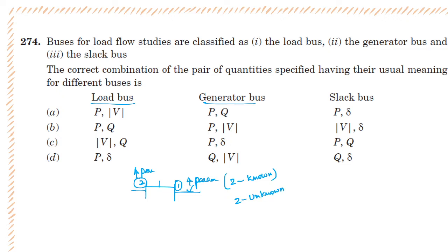How are we finding that? By using the load flow analysis, right? Now, for any bus, we should have two parameters. Suppose we generally have at a load bus, what are the two parameters we can have readily available? Generally we can measure real power and reactive power, right? So we can get these values from the load side, the receiving end side.